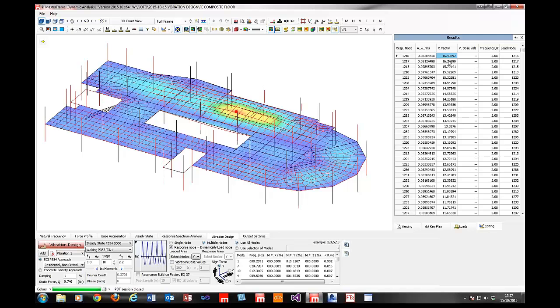So for example, if this were an office that was being used for special purposes, table 5.6 in the P354 would give a reduced response factor of 4. Certainly then also things like operating theatres would have an acceptable response factor of 1. So this is well outside the range of that, even for the normal 8 that you might want for an office or for residential purposes.